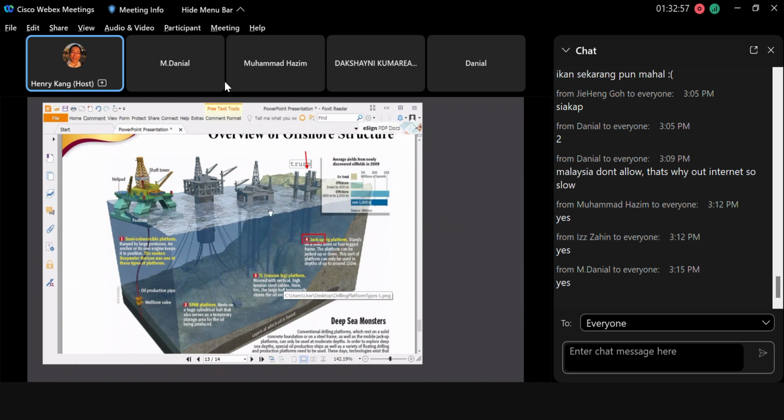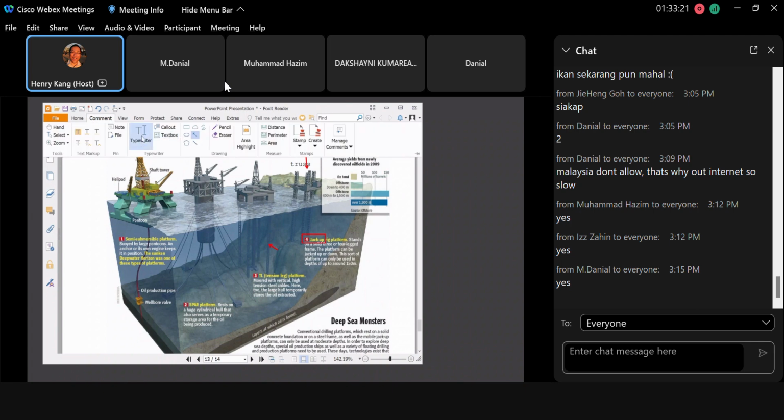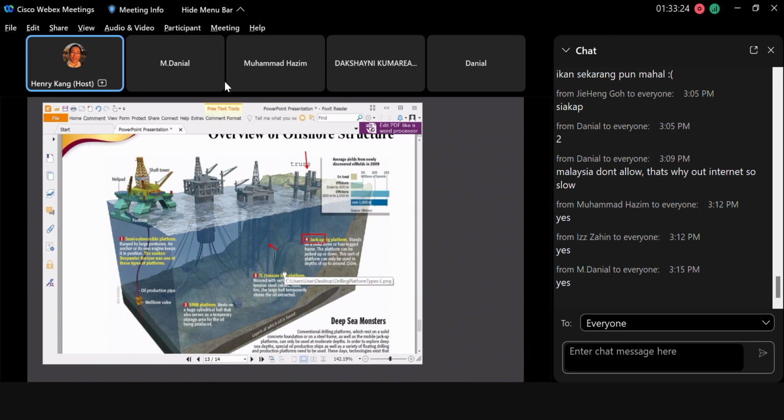In the tension leg platform, we make sure the buoyancy of the platform is strong enough so that the platform generates a positive tension in the tendons, or the legs. The tendons are normally wire ropes.